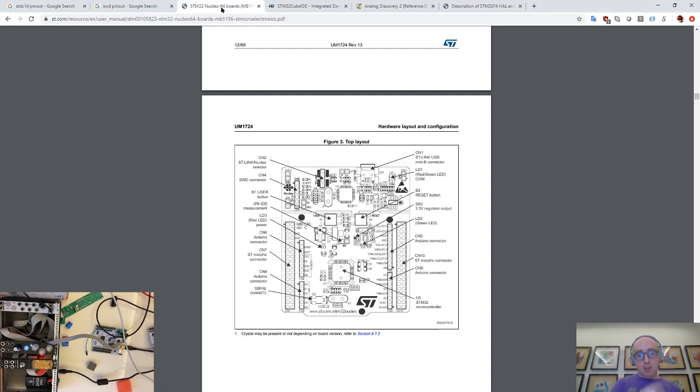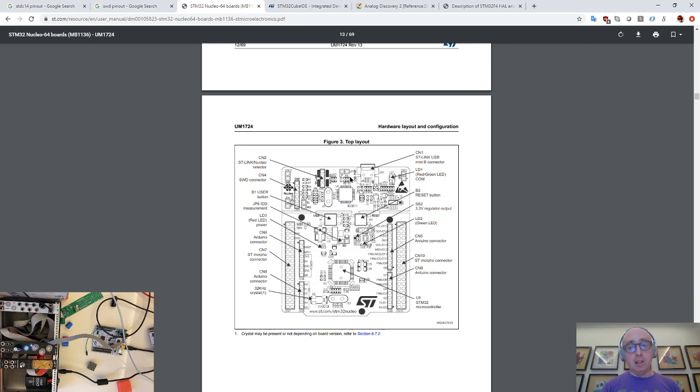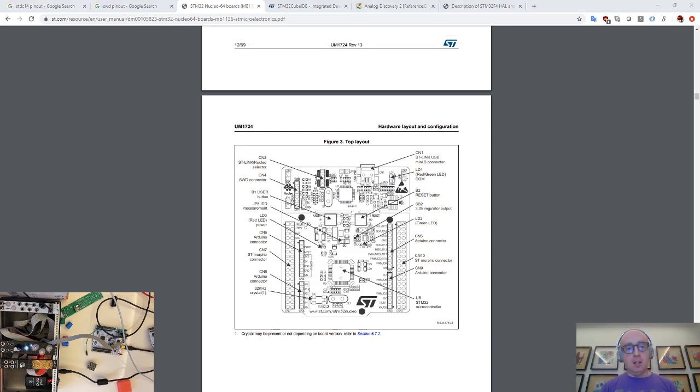So that's a Nucleo. And the funny thing is the top half, right, is a standalone programmer. So the amazing thing is this whole board is 20 quid or less, and you get an STM chip for you to fiddle around with and prototype on. And then on the top half, you get a programmer which can either program the thing on the bottom or can program a remote board.